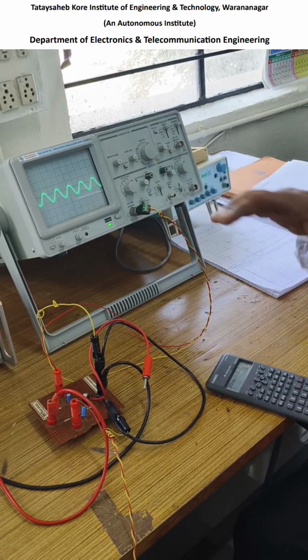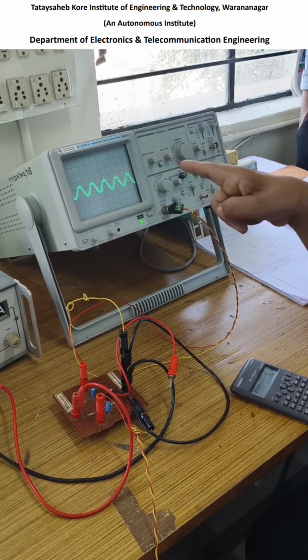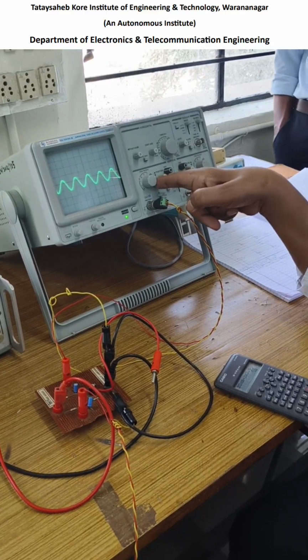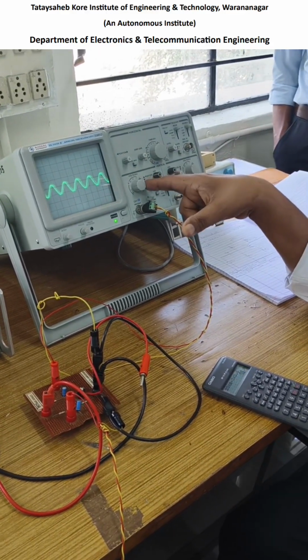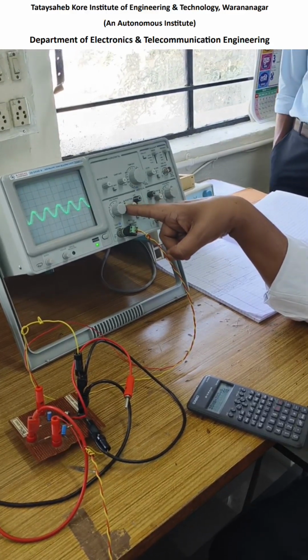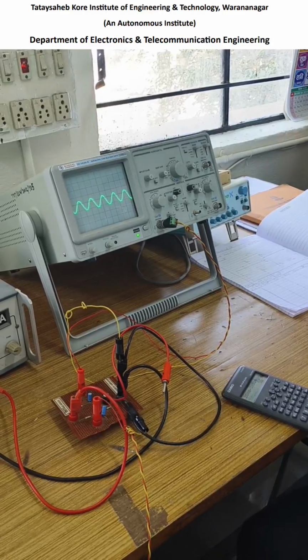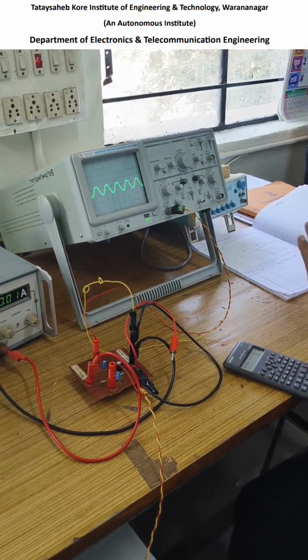1.4 into 50. Whenever you are taking the reading, take the vertical height and then multiply by the respective pointer. You will get it. Please note that whenever you are taking the multiplier, don't take only 5, 10, 20 or 50. It is in millivolt. So if you take that care, you will get the reading. Right? Now only one reading I will show. All other readings you repeat.